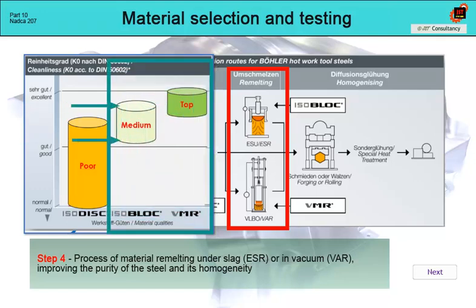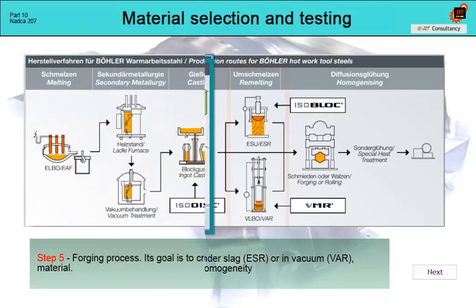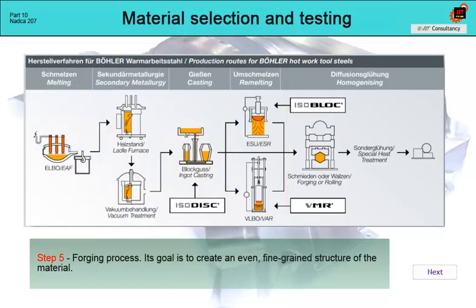This is exactly what we need for die casting dies. High and stable impact strength values. Despite all efforts to improve the steelmaking process, it is still a heterogeneous process with different properties in different parts of the ingot. This also applies to the microstructure and grain size.